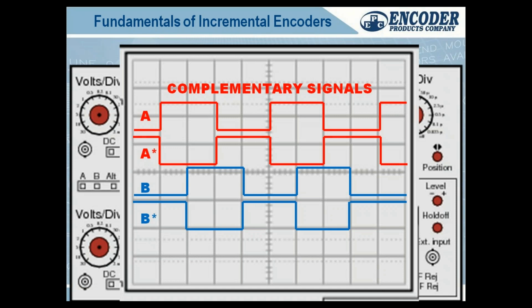If your encoder loses power or voltage and regains power, does it retain the position it was in and where it left off? An incremental encoder will never, by design. Absolute encoders, yes. And our absolute encoders and a few other manufacturers now have a technology that if you lose power and you move the encoder, when you turn that encoder back on, it will still be reporting the correct position.